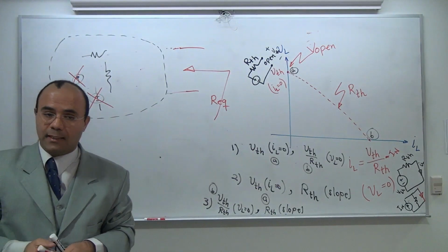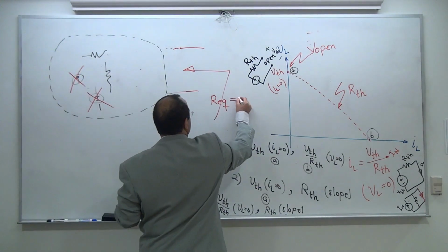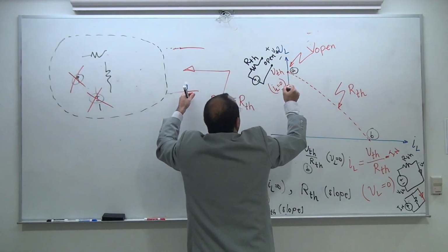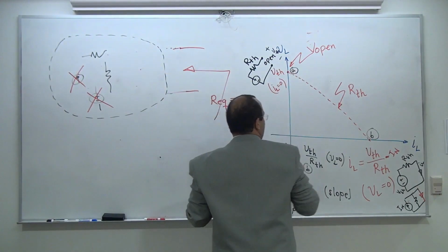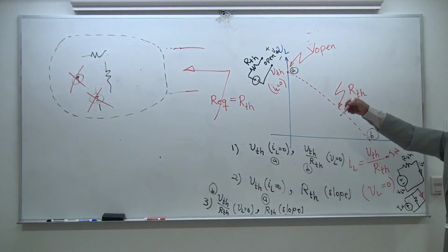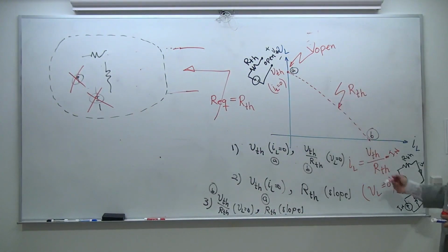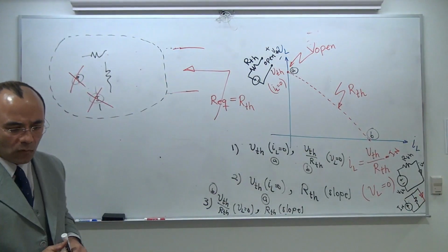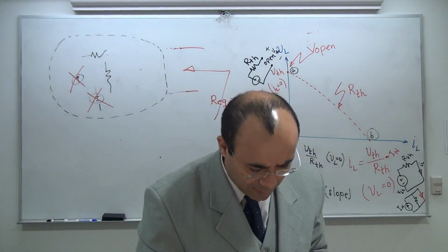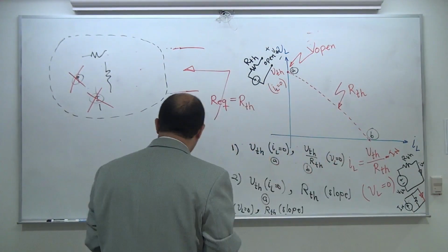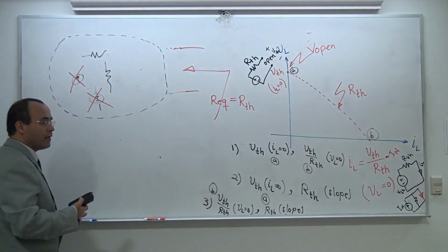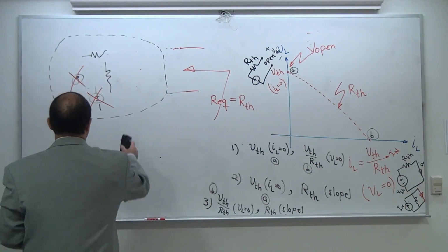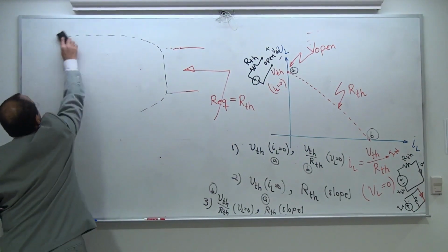You've got so many ways of identifying your Thevenin. You can tell me this, that is open voltage and R equivalent. You can tell me this, that is a short current and R equivalent. You can tell me this and make it and get it done. I'm going to go in and basically give you a number of examples. Actually, from the same example we started, it's a simple one. I'm going to solve that, then I'm going to go and solve 2 more cases so that everybody knows what to do.